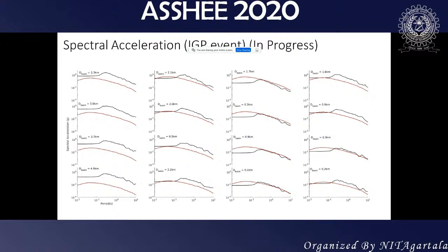What we understand is, the amplifications when an earthquake occurs beneath the Ganga basin is entirely different from when an earthquake occurs in the Himalayas. So you will see different types of amplifications. Some places will have de-amplification also. Like at 0.1 kilometer depth of the basin, you can see there is a de-amplification in the low natural periods, but for the long periods we don't see any amplification here. And when the depth of the basin is very high, say 4.6 kilometers, then you can see a huge amplification when an earthquake occurs beneath our Indo-Ganga basin.